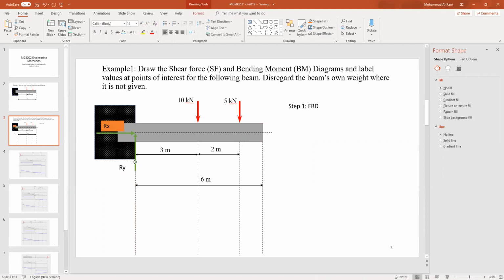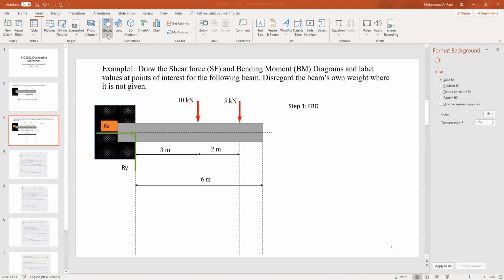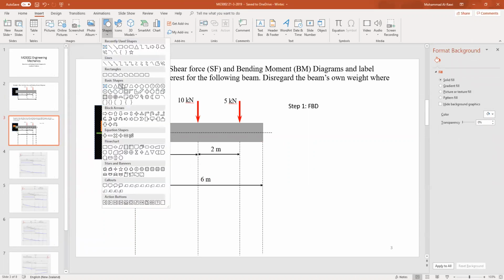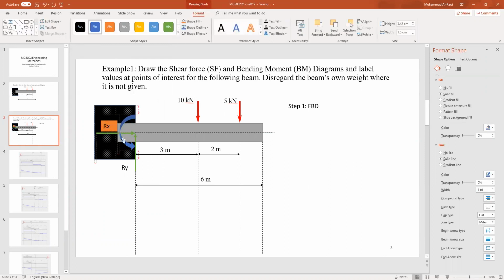Now, something new happens when you have a cantilever, which we haven't seen, for example, in fixed supports or roller supports beams. You have another value, which is the moment, and how that moment is acting. So in this example, we'll assume the moment is going counterclockwise, because I always solve it clockwise. This time I want to do something kind of different. So here I put a moment going in that direction, and I call that moment M, for example,